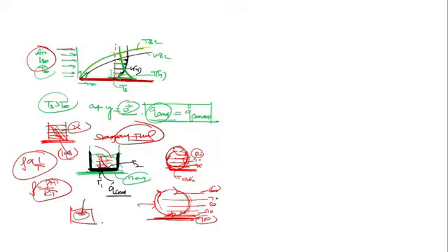So what I am saying to you, in this case whatever energy transfer happens on the wall at y equal to 0, in this example whatever fluid gets heated on the wall is directly through conduction, because the fluid layer at y equal to 0 on the surface of the solid is stagnant, so heat transfer is via conduction. But in the remaining fluid the heat transfer is via convection, because now the fluid is in motion. Is this clear?